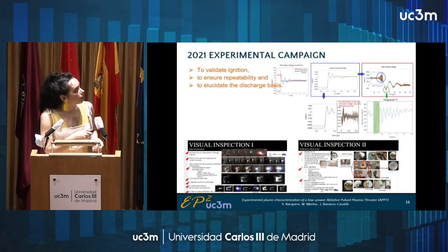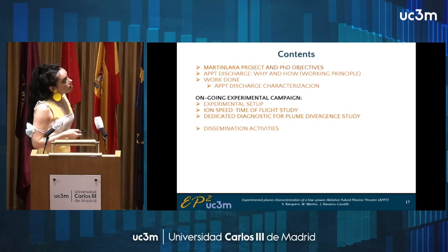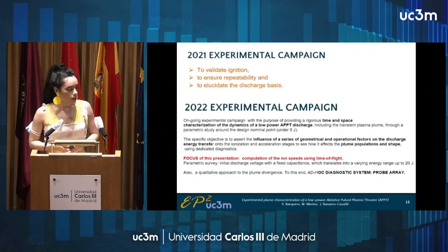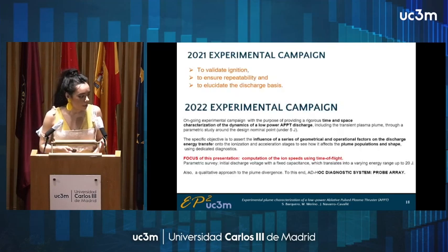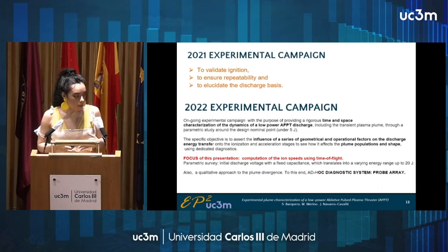We were also working with other kinds of diagnostics, such as a camera. We were observing contamination patterns. Also, we were exploring, as a first approach, the plume with Langmuir probes. Basically, it was, as I said, a first approach to this. So now we are trying to work on a more mature campaign, and what we want is to learn about the plume shape.